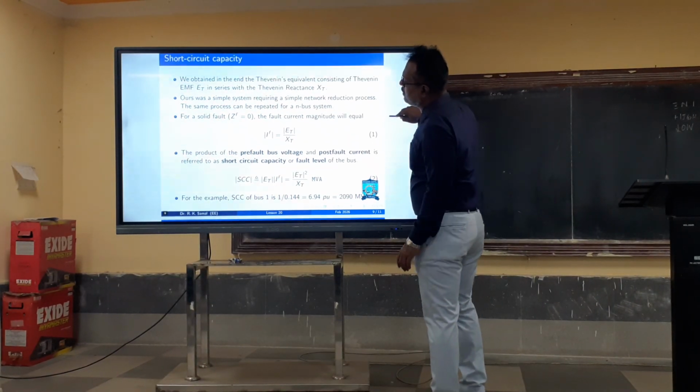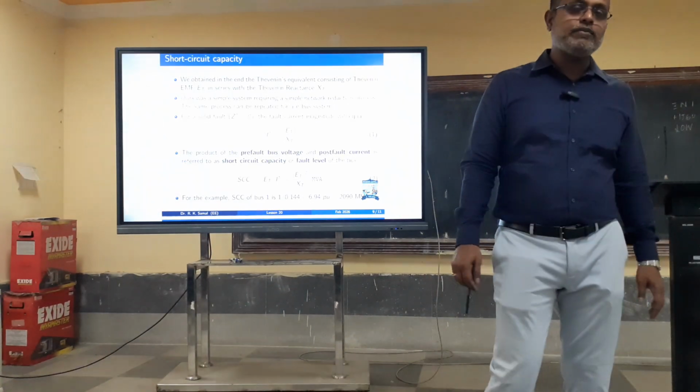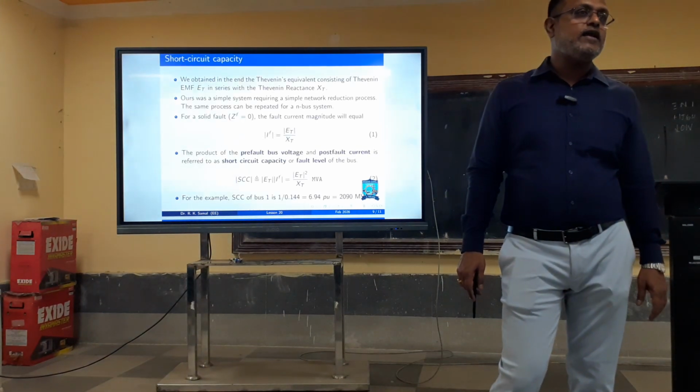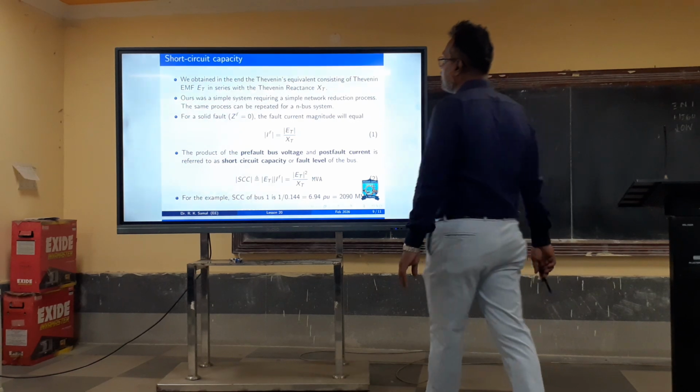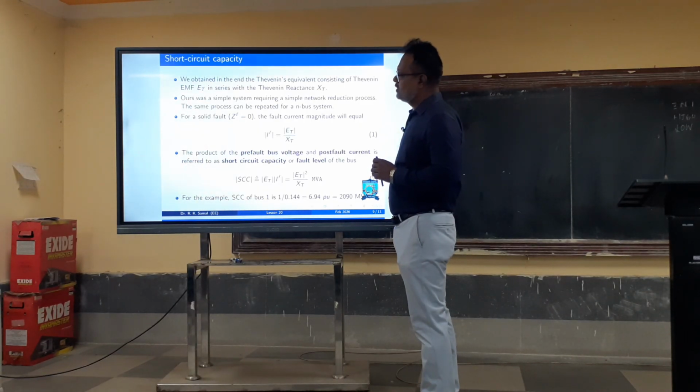So finally, what is the utility of this short circuit studies? I have been telling you, this is for finding the rating of the circuit breakers. So we obtained in the end the Thevenin equivalent consisting of Thevenin EMF ET in series with Thevenin reactance XT, right?